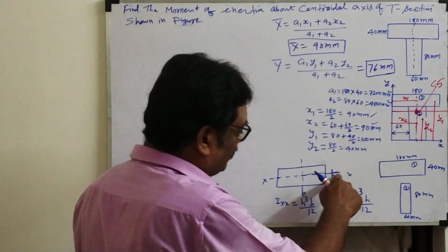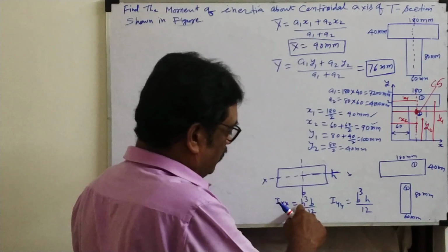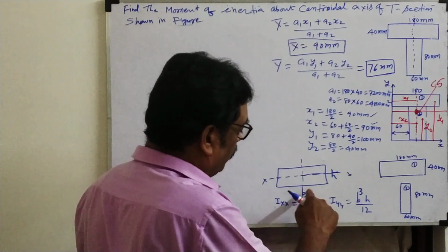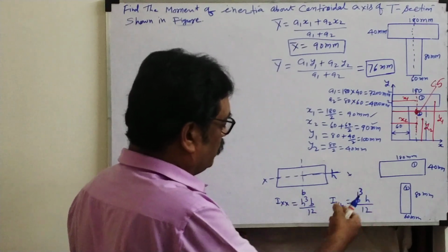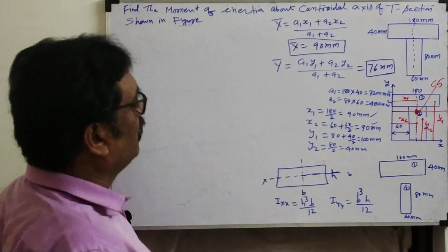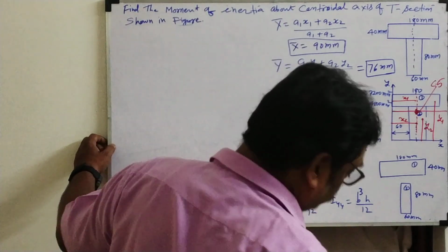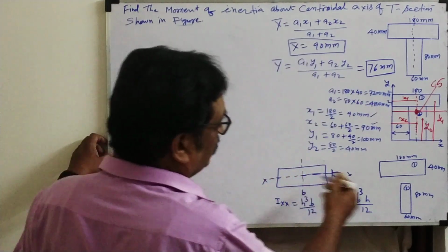So which side is getting cut, or is perpendicular to h? h cube. Perpendicular to b, b cube. So simple. Two techniques for how to remember; this is up to you. Now, we know the individual section's moment of inertia.